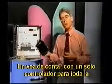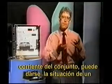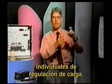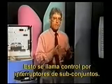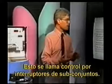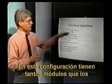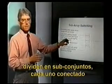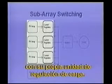Instead of relying on just one controller to control all of the current from your array, you may face a situation where your array is large enough so that you have to install individual charge regulating units. We can do this, and this leads to what we often call subarray switching type of control. Let's take a look at that for just a minute. In this configuration, you might have so many modules that you break them down into smaller subarrays, with each subarray connected to its own charge regulating unit.